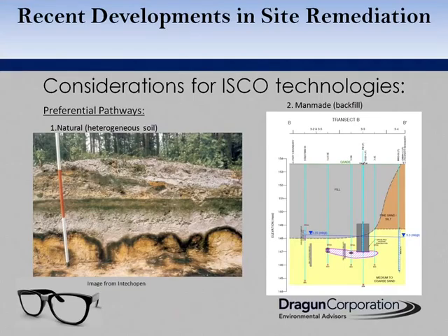Remediation at this site previously included a substantial excavation with high purge rate dewatering, and they did not conduct a detailed site characterization, the importance of which we learned last week. They were unaware of the large LNAPL plume floating on the water table. The high rate of dewatering caused the NAPL to smear below the water table, which you can see as a purple dashed zone on the right conceptual site model on this slide. And as previously mentioned, 90% of the site was successfully remediated using ISCO methods.